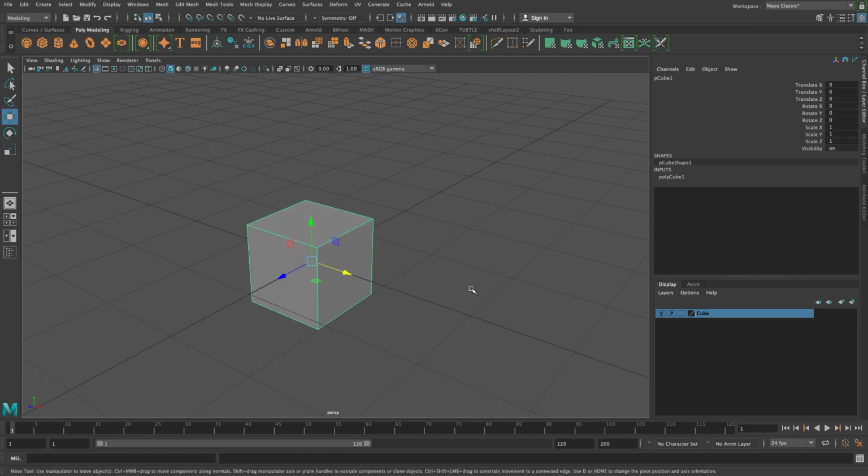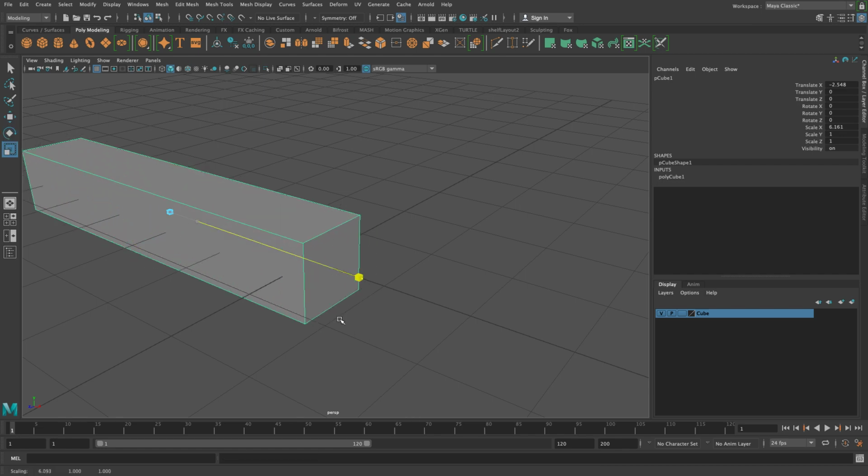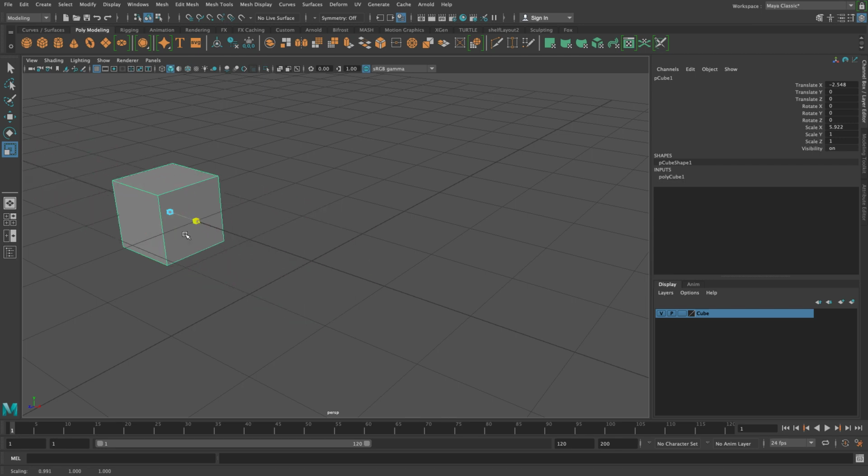But there's another thing you can do with primitives. When you are just manipulating things as a whole, and you decide to rotate them as a whole, or scale and play with them as a whole, you are interacting with that asset in what's called object mode, okay? There's another mode called component mode.